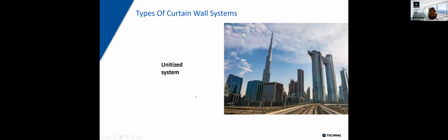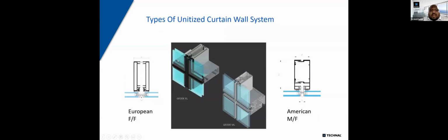So that's a quick wrap of stick curtain wall systems. Now this gives me an opportunity to talk about unitized systems, which is really an interesting topic. In the unitized system, we have two types. We have the European female-female system, and we have the American male-female system. In principle, the major difference between the male-female and European system is the male-female system has more opportunity to move. So when you have high-rise buildings and you have a lot of interstory movements, your male-female system is preferred.